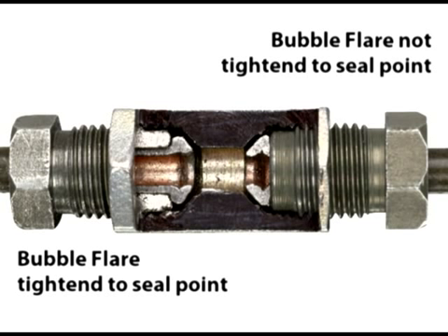You cannot use bubble flare fittings with either of the other two types of flares without using an adapter that will seal to both mating surfaces.